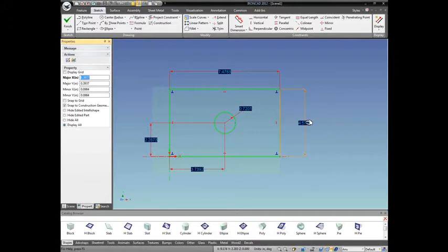Was there a visual when you went to that corner to indicate for sure that that was the point being recognized? I didn't see that. No, it's just the hand cursor going over it. The points don't really light up, but if you have a little hand over it, that means you've got a point, and you can right click. The little hand icon really tells you. And then you can see, like here, the cursor shows a line next to it. Here, the cursor shows a circle next to it, and then for a point, it just shows a little hand.